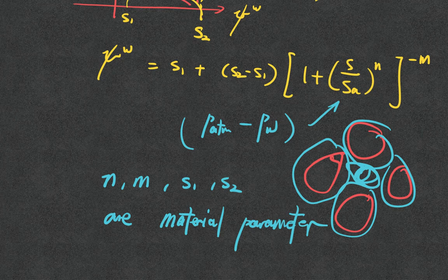To give you an example, if I have the same water, but on a plastic domain and in a clay domain, I have a different retention curve, with the same water and the same air. On the other hand, if I have the same solid but I change the air to oil, I will have a completely different water retention curve. It's the surface energy difference between all three of them that gives us the retention curve. Brine water and clean water would of course make some difference. And here we don't talk about the possibility of the solution getting crystallized.